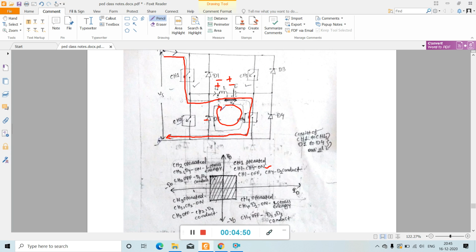See, note one point here, that the type E chopper operates as a step down chopper in the first quadrant, and in the graphical form I have shown it here. This is the first quadrant operation shown here. This is the first quadrant where V0 and I0 are both in positive direction, and that's why it operates in the first quadrant.